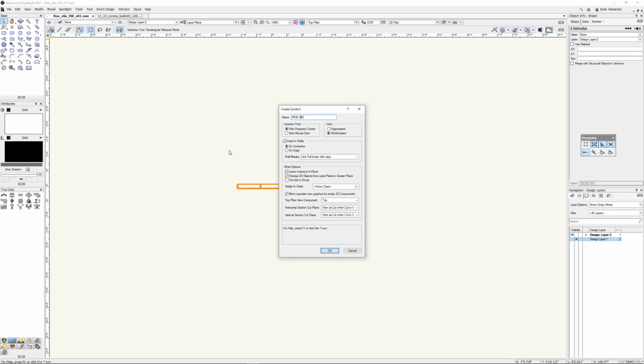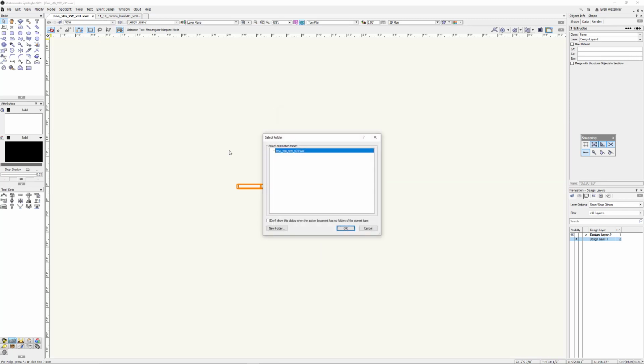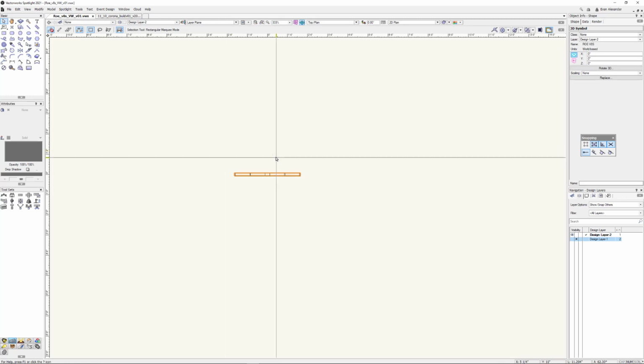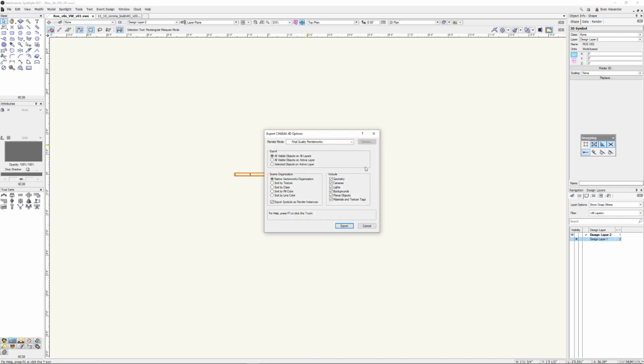And there we go. And we'll say, okay, we don't care. And there it is. Okay, so now that we've got this, let's go ahead and export this to Cinema4d. Now, in this case, I think final quality Renderworks will be okay because everything is square on this. We didn't put in any curves or micro bezels or any of that stuff. Native Vectorworks organization is great.